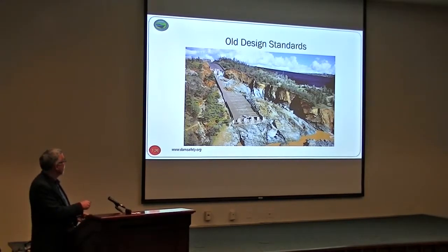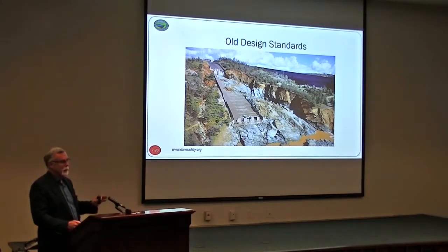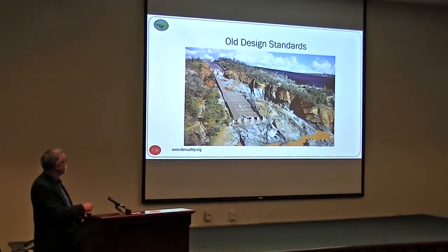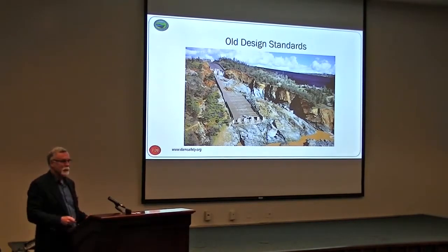It got out, collapsed, and then ran around this side over here. They're spending over $1 billion, and they're about 99% complete with putting in a new concrete spillway, and then the spillway over here, they're using RCC to reinforce to prevent erosion. So this was not a dam incident, but it was a spillway incident that could still endanger 2,000 people's lives downstream.